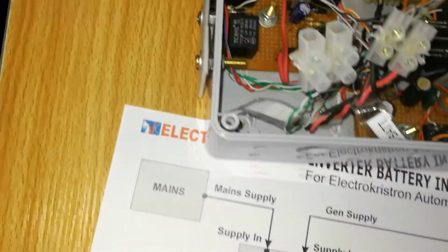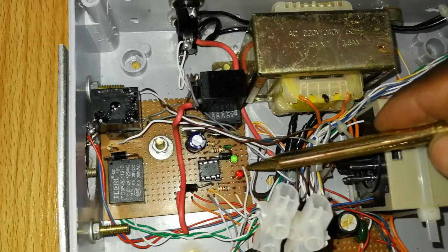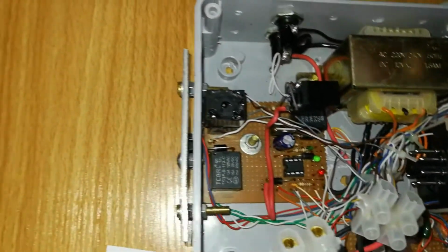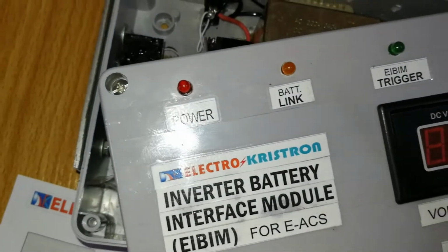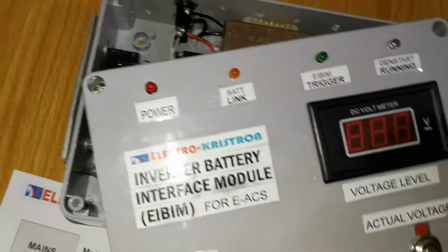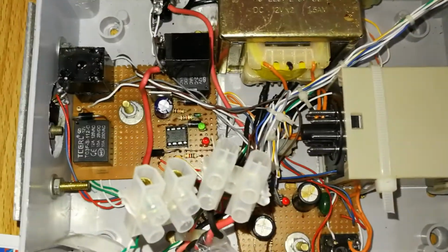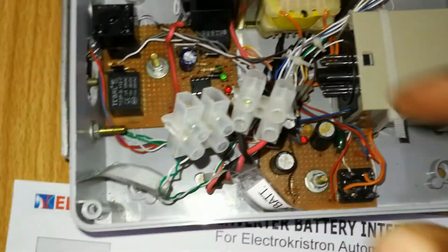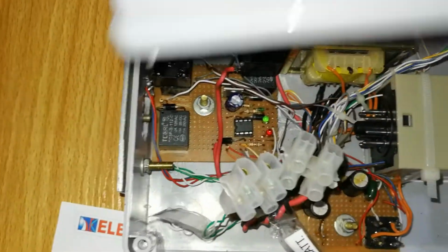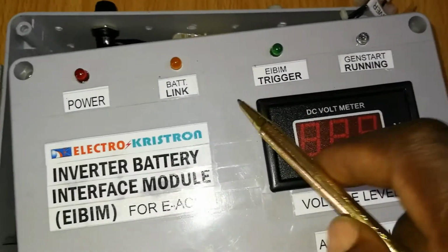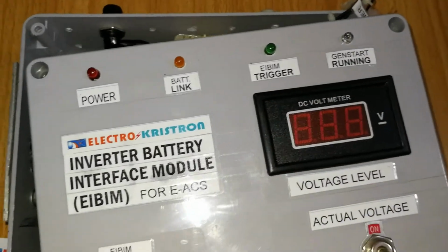You also have another one here. This red one here is linked to the back link. The moment you connect your batteries for monitoring, both of them come up. The inner ones are good for when you are setting up, so as you are doing your connections you see them come alive immediately. But once the system is covered up, you can still monitor everything from the indicators on the front.